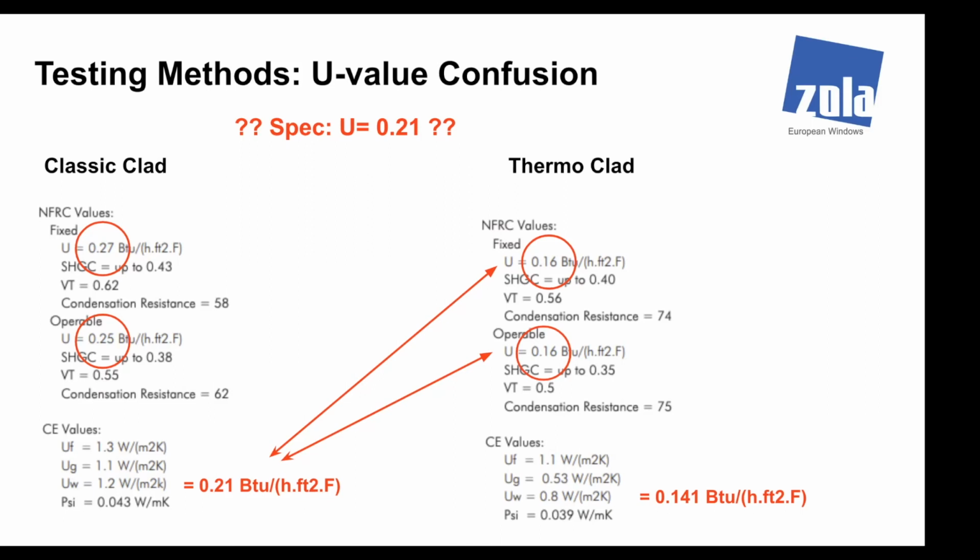This is tested for our standard product, to be perfectly honest, which for our glass is going to be a 444 with a window at a certain value, which is like 60 inches high by 34 inches wide, whatever their testing size is with our standard glass. We, of course, have dozens of different pieces of glass. So larger windows are going to have tempered and a 6 mil, and sometimes we might throw in a lami for structural, and then we have the acoustic. All of those glass and the frame combinations, those don't specifically have NFRC testing values.